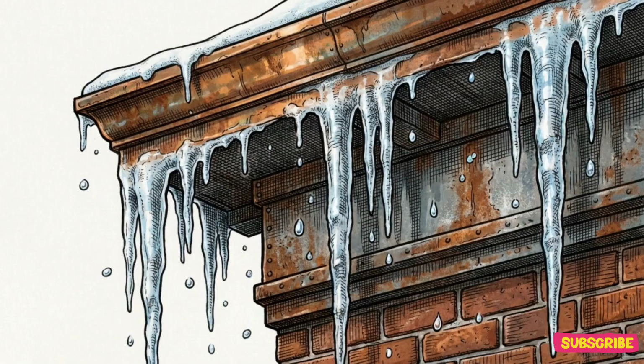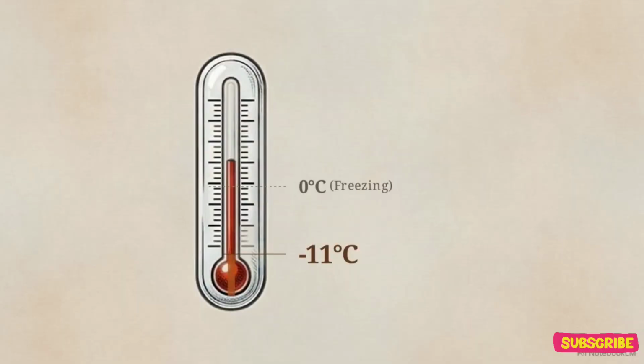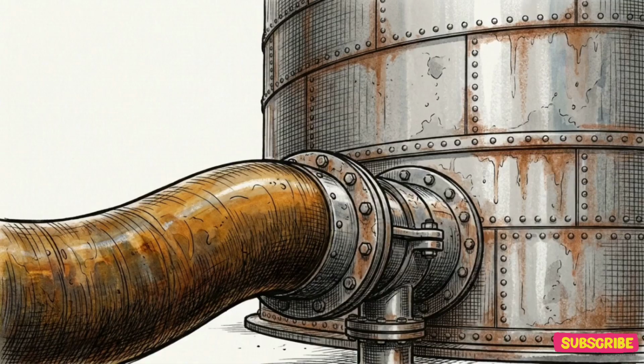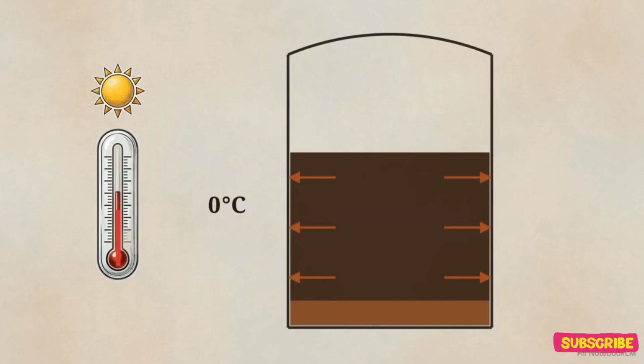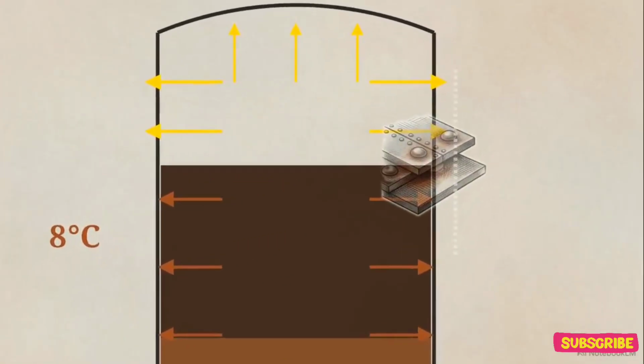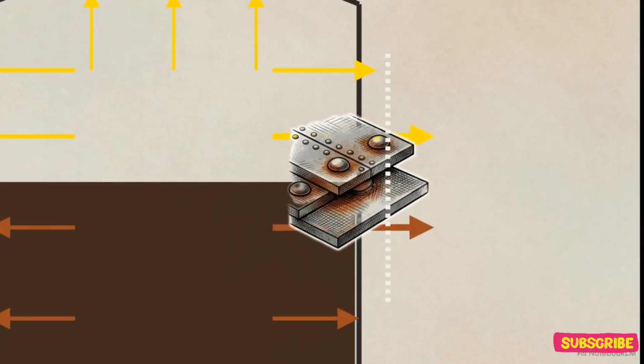In the days leading up to January 15th, Boston experienced a rapid ambient weather shift, jumping from -11 degrees Celsius up to a warm 8 degrees. Around this same time, the facility pumped a fresh, warm batch of molasses into the bottom of the already full, heavily pressurized tank. Warm temperatures initiated localized organic fermentation within the molasses. This generated massive volumes of trapped carbon dioxide gas. The expanding CO2 created new pressure vectors against the roof, adding extreme, uncalculated dynamic force that completely exceeded the structural limits of the riveted joints.